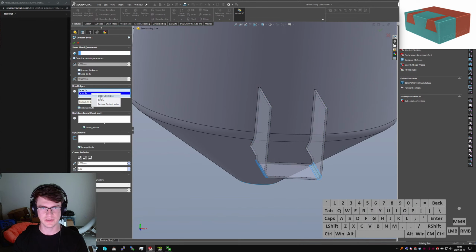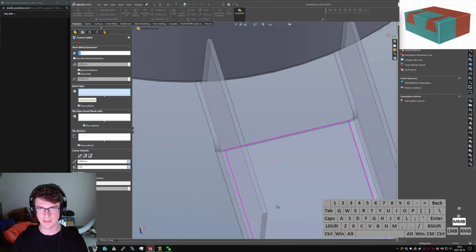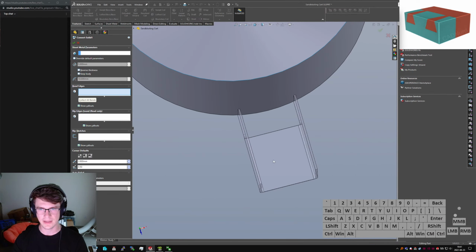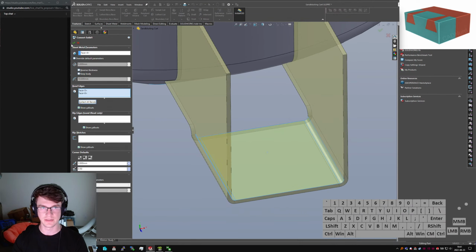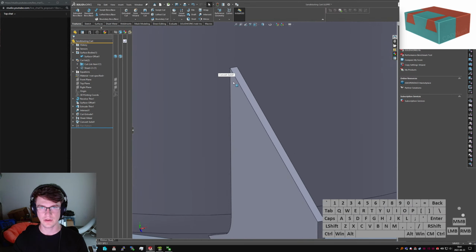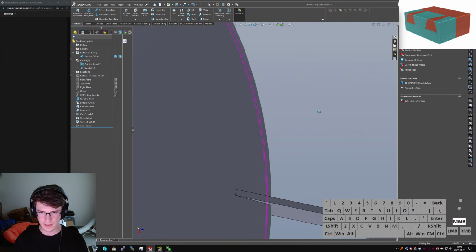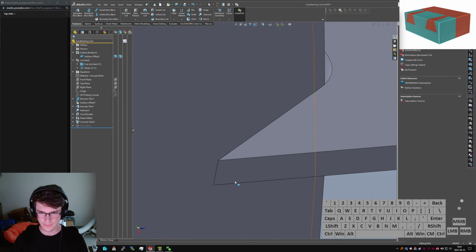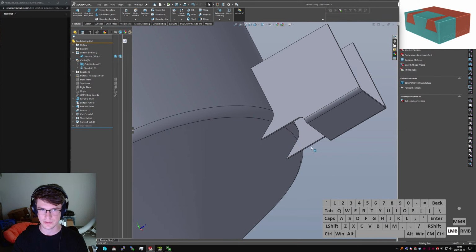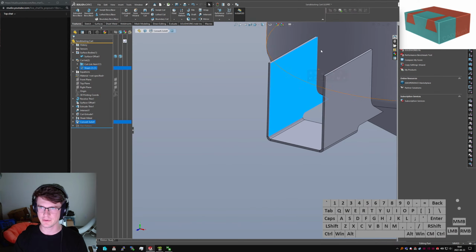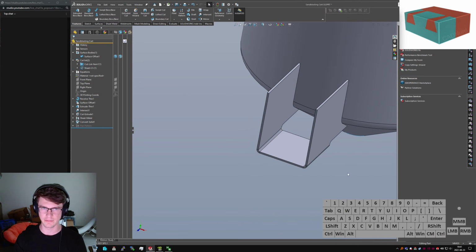Okay, so by selecting the outside there, it made the part thicker into the way, and that's not really what I want. If I start from here and then collect all bends, I wonder if it'll... It did! Yeah, cool. So now, we can see that it'll touch, but it won't intersect inwards. What I did there was basically just change the side that I wanted the sheet metal to call its, I guess, root face, really? So that it's using this interior face as the definition for the flat part.